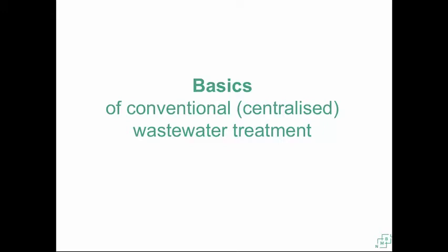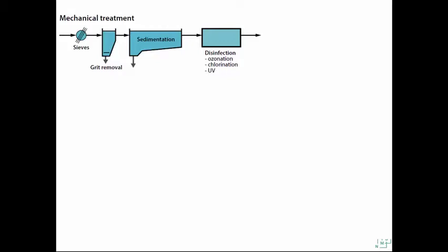Pernilla did a good introduction to the wastewater quality and also the basic treatment concept, primary, secondary, and tertiary. I would also like to quickly go through the systems in a different way, like mechanical, chemical, and biological processes. I'm sure most of you know details about these processes, but I'm also aware that some of you don't have this background. So in order to understand the rest of the lectures, I will use this time to go through the treatment processes. The target in a wastewater treatment plant is to remove organic matter, which is coming from our toilets and from kitchens, remove phosphates, which is coming also from the same sources, and to remove nitrogen and particles. These are the four things that we are going to remove.